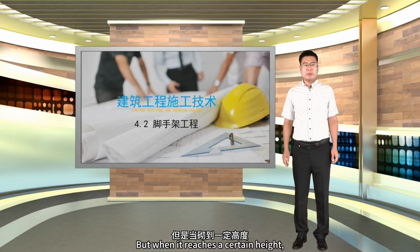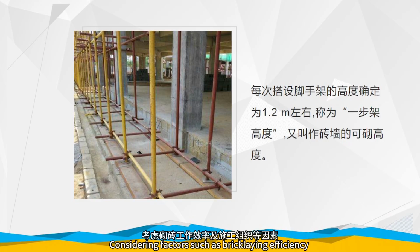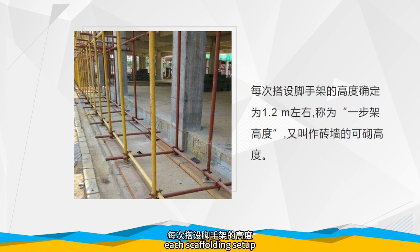But when it reaches a certain height, workers' efficiency decreases significantly, and labor intensity also increases. At this time, scaffolding must be erected to meet the requirements. Considering factors such as bricklaying efficiency and construction organization, each scaffolding setup is typically about 1.2 meters high, referred to as the one-step height, or the masonry workable height.